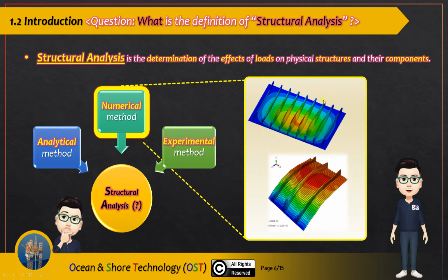So it's like these finite element examples, where they have applied the load, and you can see the von Mises stress or the displacement. But don't forget that the finite element method, or any numerical method, should have at least a few cases validated with analytical and experimental studies.